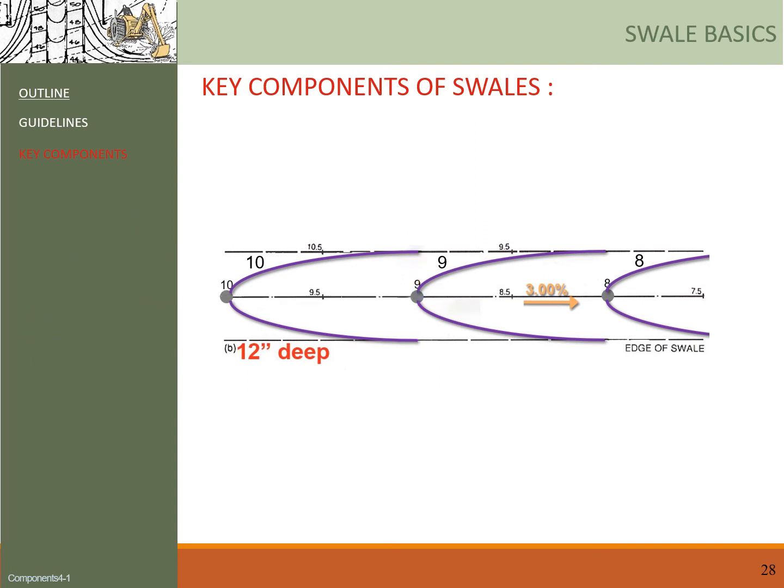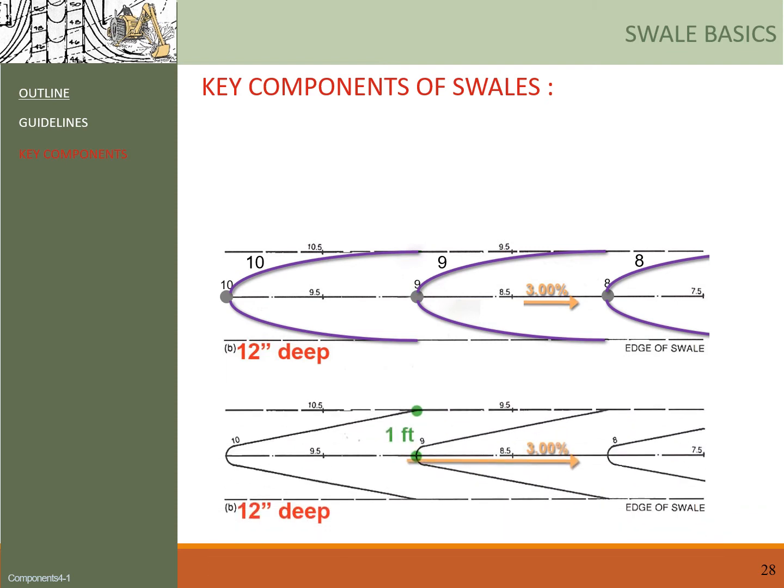You may have noticed that the contour shape that I just drew is a little different from the example directly from the book. That was a little intentional. I just want to point out here, for your exercise, we're less concerned about the exact shape of your contours. Instead, you want to make sure that these key connection points for the contours are correct, both their locations and their elevations. Okay?